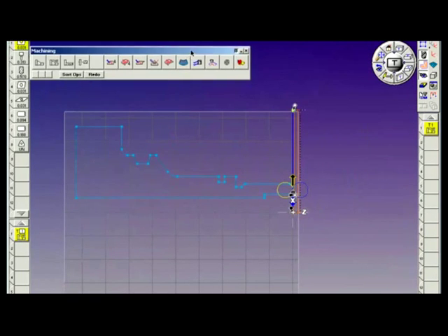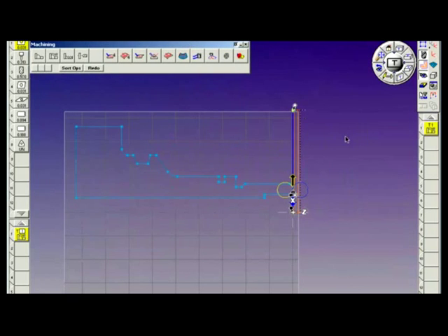I'm going to go ahead and keep it. And in order to lock in the tool path or keep the operation, you deselect the operation tile on the right by clicking an empty tile, and this locks in the operation. I will now click off the part to eliminate the markers and the tool path. And the process on the lower left is going to be used to rough turn this part.